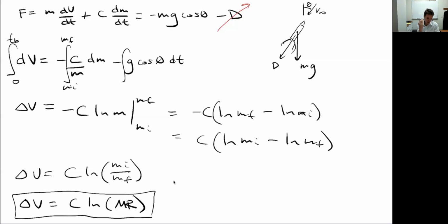And the whole purpose of the rocket was to deliver that payload. But to make that happen, to get it out there, I've got to have massive amounts of fuel and then as minimal structure as I can to make that happen. So for example, the Saturn V, its payload fraction, meaning the mass of the payload relative to the mass of the whole rocket, is 4%. And the space shuttle is about 1.5%.